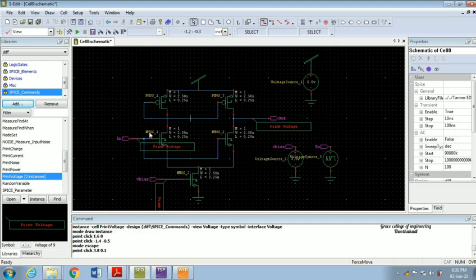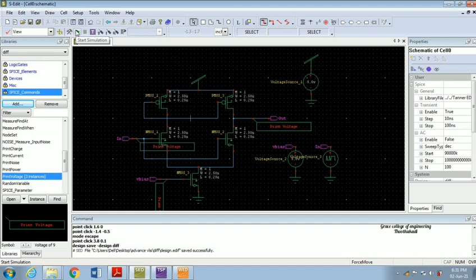Ensure that for our transient analysis we have changed our input. For our AC analysis we have to give an AC input, and also in the setup simulation commands we have to set the AC analysis unchecked. So be careful with it. We can run this one.